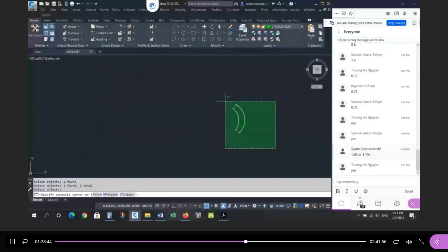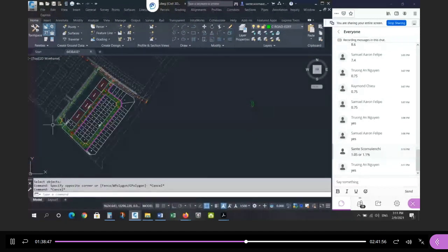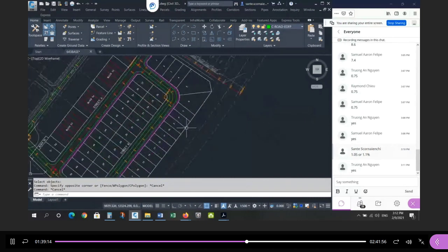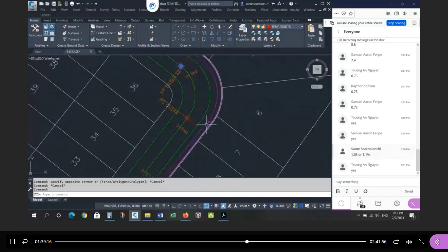You should do this calculation for all 3 elbows and satisfy yourself that 1.1 works for all of them, or 1.05 works for all of them. Okay? And try and use a standard number. Use the same value all the time if you can, right? That way it's typical, right? So figure out each one, round up so that you're higher than each calculated value. So I think 1.1 will work everywhere. You convince yourself, though. I'm not going to do the other calculations, okay? You guys try them. All right, so I'm going to use 1.1 on the profile between this point, and